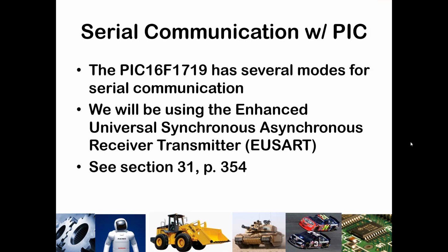Serial communication with a PIC can be done in a variety of modes, and in this course what we are going to use is what is known as the USART, or the Enhanced Universal Synchronous Asynchronous Receiver Transmitter. And you can read a lot more about this in section 31 of the data sheet, beginning on page 354. Throughout the rest of this lecture, I will break down the various registers associated with that, what those different bits do, and how we can set up for both serial transmission and serial receipt of data.